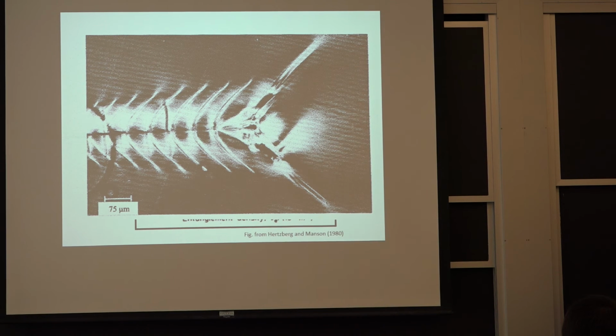Very, very tough, very, very deformable. Even if you put a notch in it, it gets this mechanism to blunt the crack and allow for a lot of deformation. And really, one of the main reasons is you don't have the spherulites and you don't have the crystallites in there to affect your behavior.